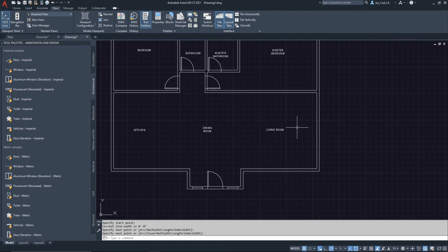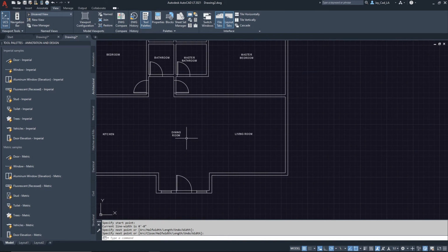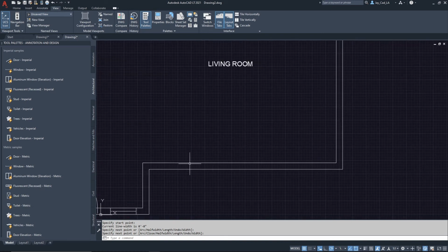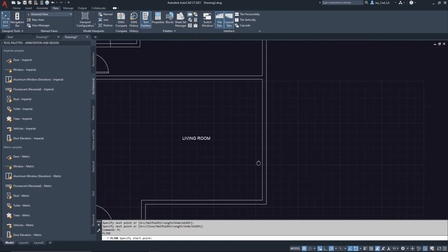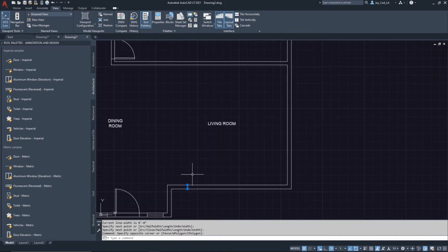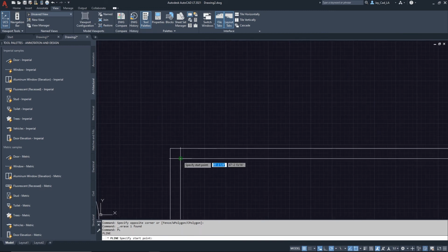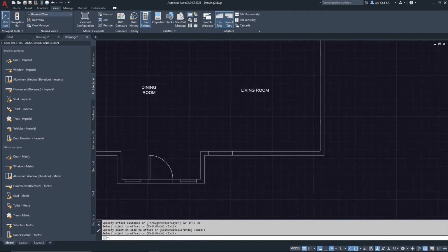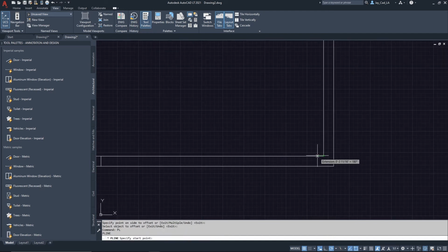And then here for the living room, we didn't place everything yet, but let's say we have 2 wide windows on this side, and then we have a large sliding door over here. So let's say here 2 feet from this side. Actually, let's keep the windows more to the corner. So I'll delete. Let's actually put one here. Let's delete this line. Let's just do a simple one. Let's do 6 inches, and then I'll offset by 3 feet to the right, and then I'll do the same from the other side. So let's say 6 inches here, and let's copy here by 3 feet as well.